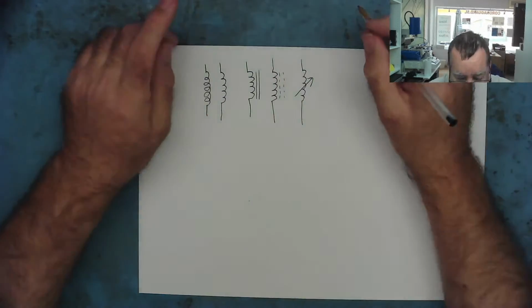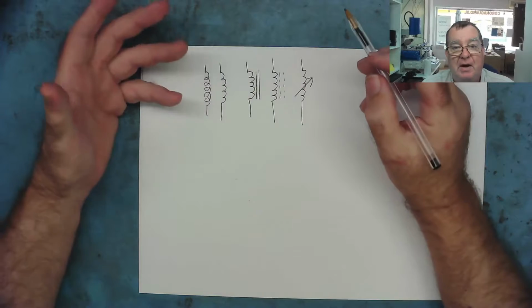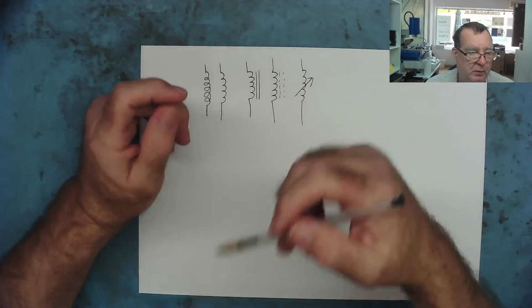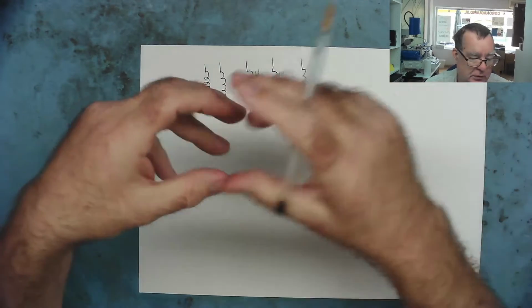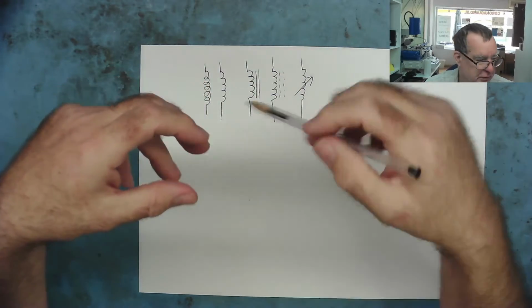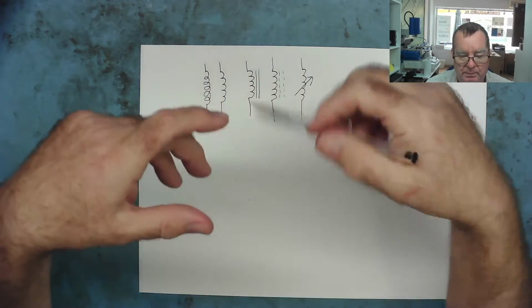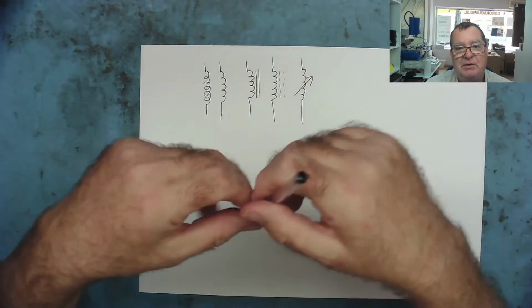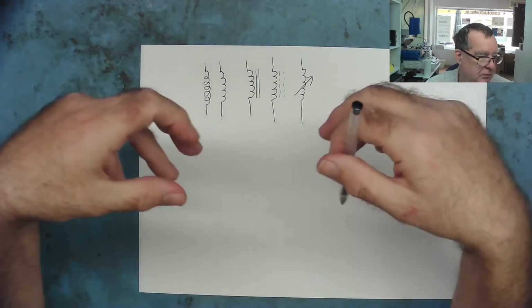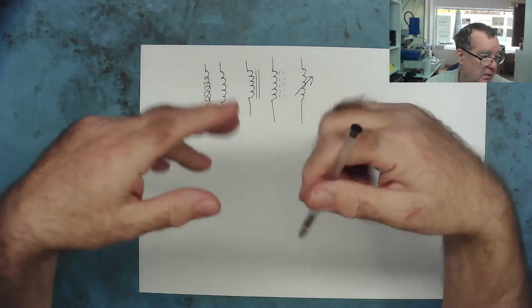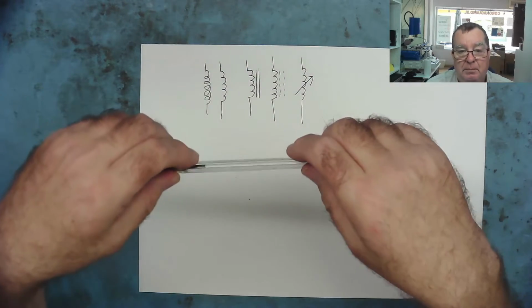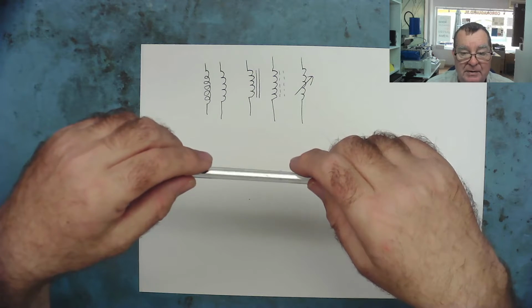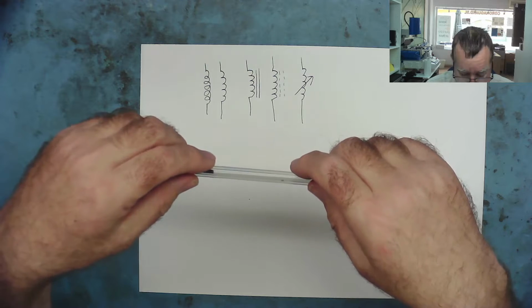To understand why the symbol looks like this, we need to understand what an inductor is. Basically, an inductor is just a piece of wire wrapped round and around some sort of former. The former could just be a piece of plastic or paper even, or, more commonly, a magnetic material. It could be a solid metal bar or laminations of solid metal, or it can often be a substance called ferrite, which is basically a mixture of ceramic and iron dust or particles.